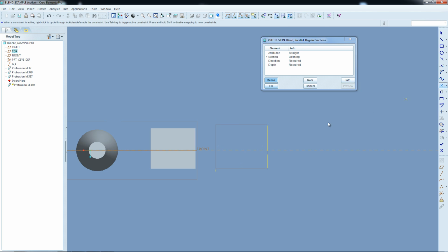And in our case we're gonna just sketch a single point, which if you want a nice symmetrical pyramid, that really has to be locked down so that it's in the middle point in both the side here and this side here. So if you just draw some lines like that, they're snapped automatically to the midpoints there. That's what these M's signify.